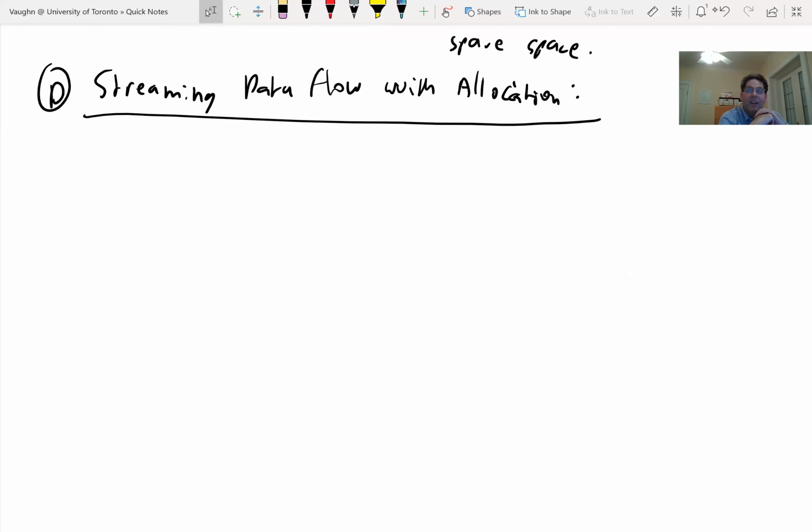Whereas these feed-forward designs, you can essentially pipeline them structurally. You can just take all these signals that cross a cut line and pipeline them all, and you don't even understand what the circuit does, right? You can just mechanically pipeline it. You can't do that with loops. For a loop, if I were to pipeline it, it's broken, so I need to understand what this control logic or loop logic does, and I need to change it.